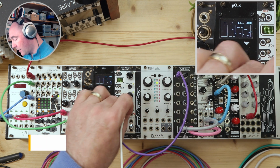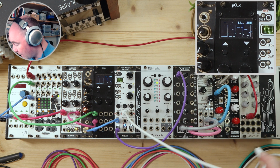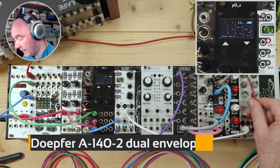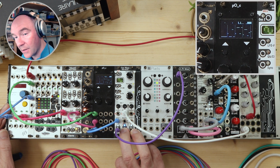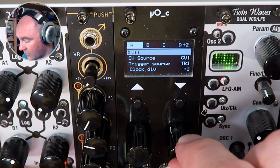The nice thing about the twin waves is it has a built-in VCA. So we can actually just gate that with this envelope over here that I'm going to be firing off using a gate that I've just taken off that mult. So whenever the gate fires an envelope's here, it'll trigger the VCA inside twin waves and we should hear a sound. Let's just go up and turn off quantization right now.